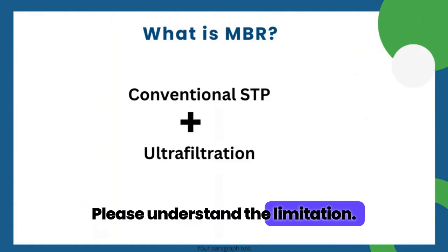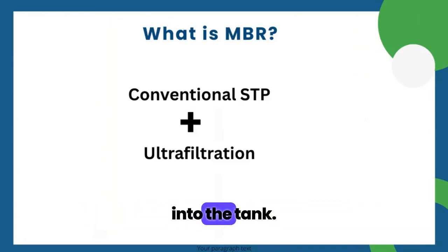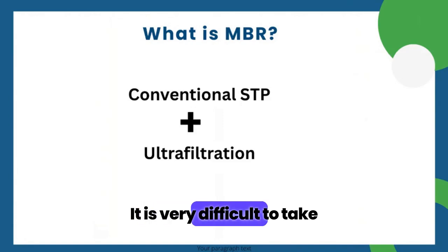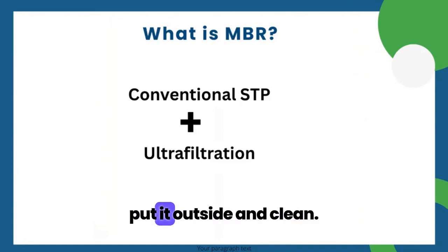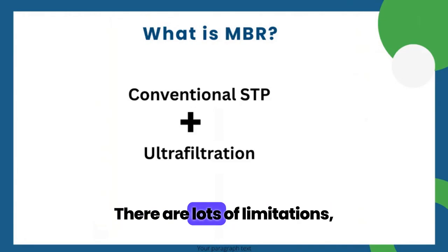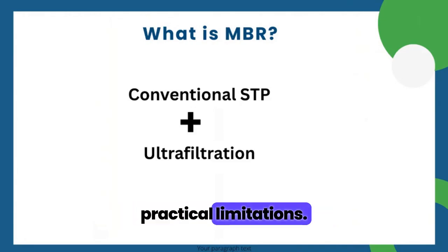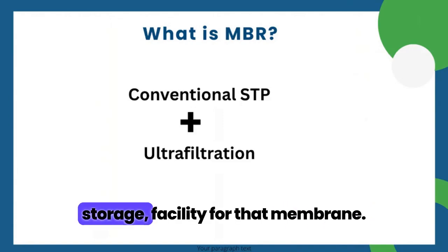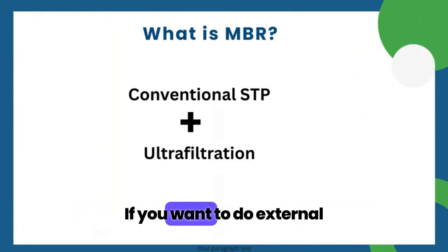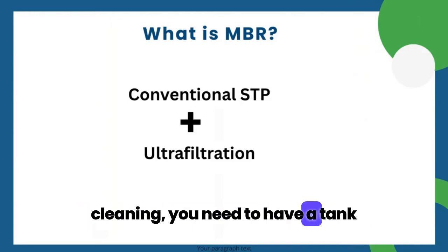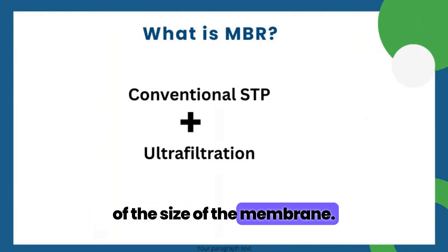Please understand the limitation. You are putting the membrane into the tank. It's very difficult to take out the membrane again, put it outside and clean. There are lots of practical limitations. Again, you need to have a separate storage facility for that membrane. If you want to do external cleaning, you need to have a tank of the size of the membrane.